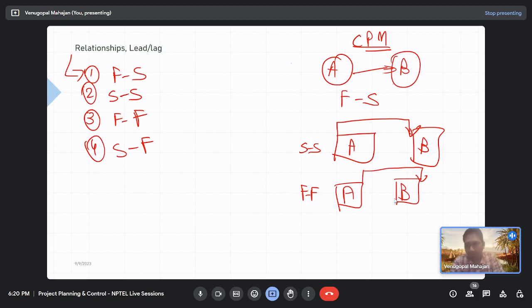Construction itself. Tying of reinforcement and placing of concrete. Okay. As soon as you start tying the reinforcement, can you start placing the concrete if the formwork is already done? No. After completion of reinforcement only, you can start the concrete. After completion of reinforcement only, we can start the concrete. Okay, after completion of reinforcement only.